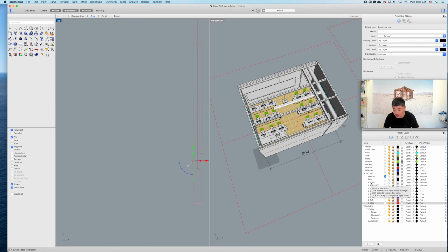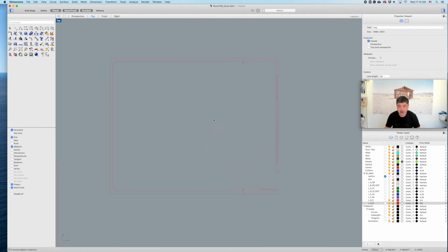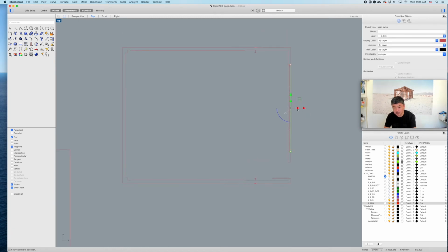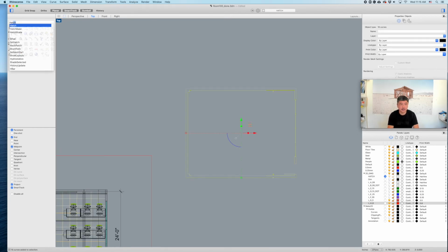Okay, and so this one actually is here. Okay, so select this. What we can do is draw hatch inside of our doors and walls. I don't think this line should be here, because this one should be on the lighter layer, so I'm going to change it to the 0 E layer. Okay. So I am going to select all of these and hatch.